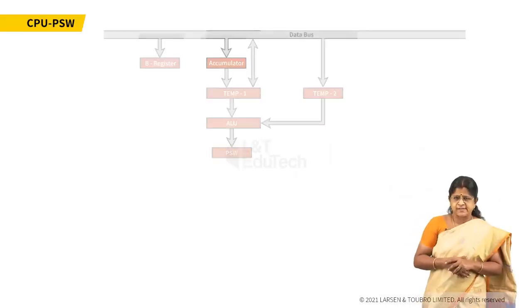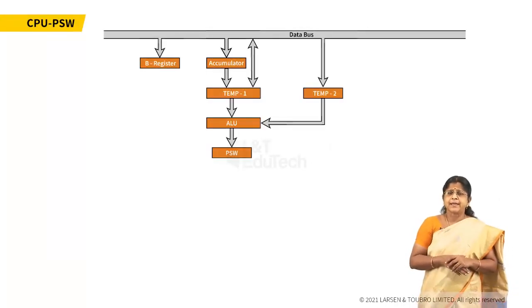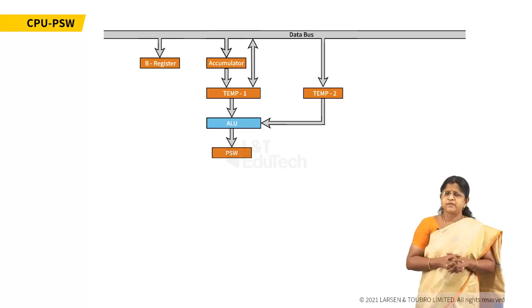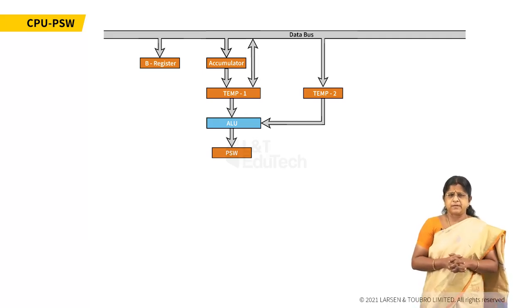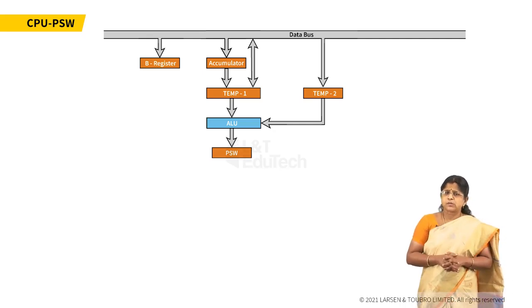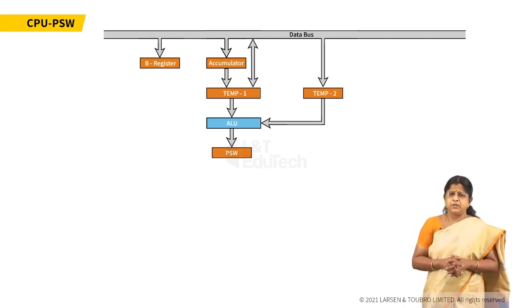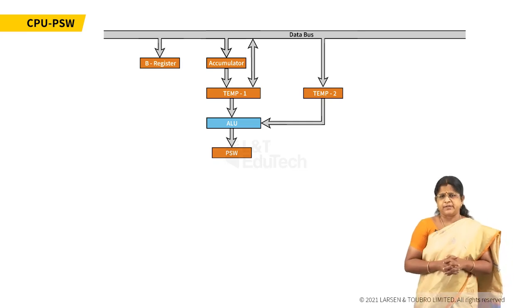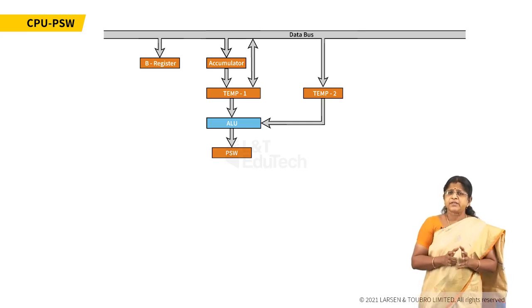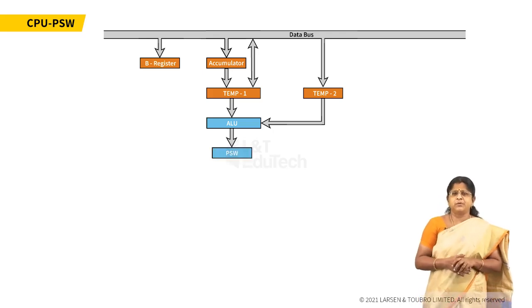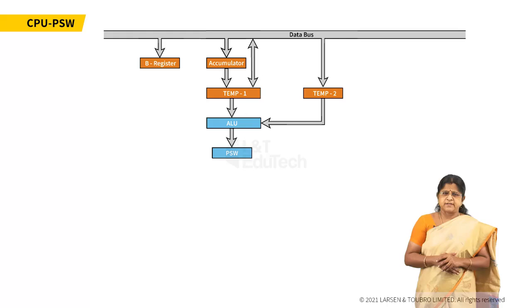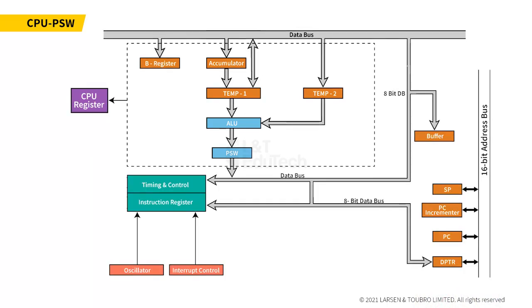The fifth block of consideration in our architecture is ALU. This unit consists of adders, comparators and multipliers to support the arithmetic computations. Also, combinational circuits are available to perform the logical operations. Their computation results directly impact the status of the PSW register. The next major block of interest is instruction register, available to receive the instruction opcode, and timing and control block.